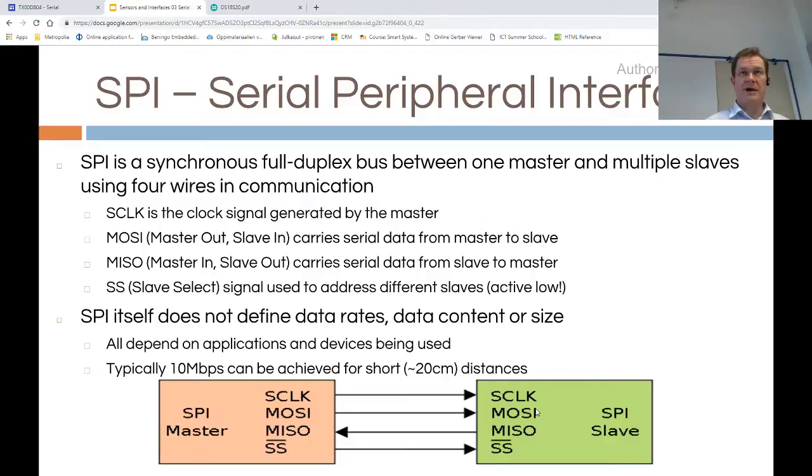I2C requires two, and it still has some limitations on the bus length because of the capacitance of the wires and the weak pull-up resistor, the weak one state.